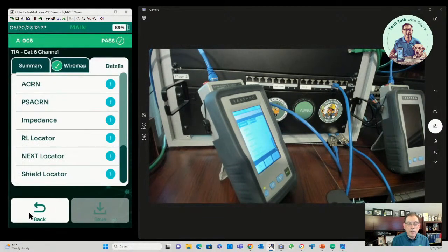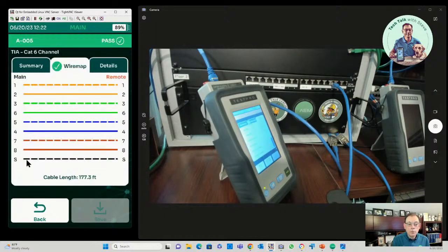Now, one of the things that you can see in a test like that, one that passed, this one, the anomaly wasn't enough to show it, but if we had one where the difference was enough, you would get the little sine wave indicators here that there's something changed in the shield right out at about that patch cable, like 2 meters roughly, if that's the length of your cord.